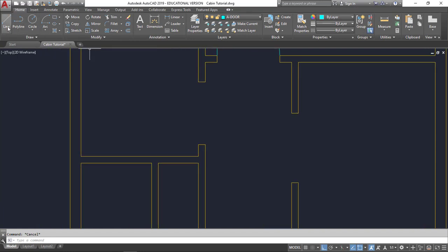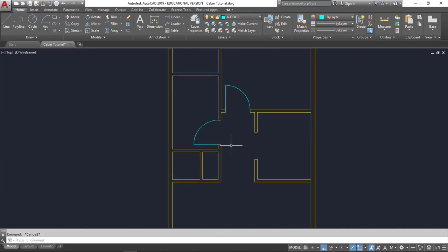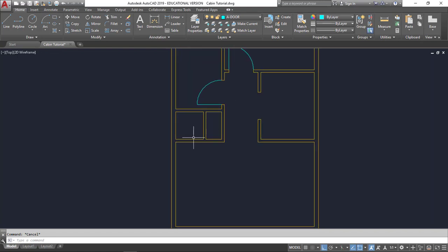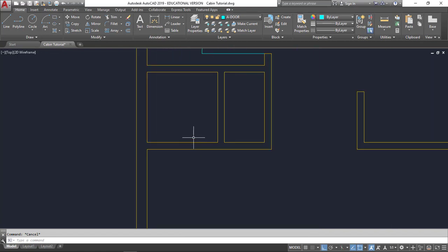Okay. Click my line tool. I'm coming out 2 feet 8 inches. So counterclockwise, I would start at the wall. Let me go the opposite way and show you what happens. Start, center, end. So if I started here and went to here, you notice it draws it counterclockwise from my starting point, which was here, which is not what I want. So escape, start, center, end, start, center, end. We're good there. Again, I like zooming in, making sure that I can see everything easily on the screen.